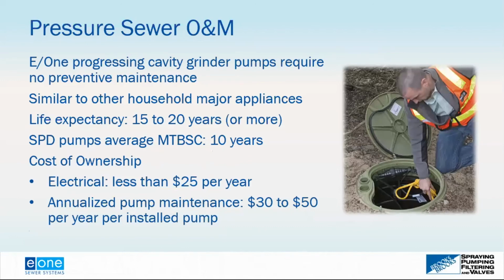So with E1, if you remember back from, I think it was part 2 of the webinar, or maybe part 1, one of the first 2 parts, where I did a little more focus on the differences between centrifugal and semi-positive displacement pumps. And there is a difference. So it's important to incorporate that distinction, that the progressive cavity grinder pump requires no preventative maintenance. The same can't necessarily be said for centrifugal pumps. Centrifugal pumps operate over a wide range on their pump curve, so that can create some problems. But even if you're looking at a centrifugal pump, the maintenance on it is not as bad as some people tend to fear.